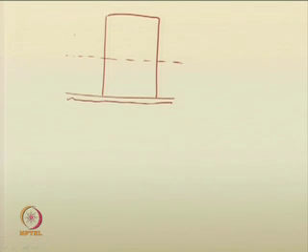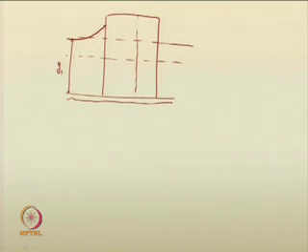So, various flow depths we can suggest now. Say at section 1, let us assume that it has the normal depth y1, then the flow rises due to the obstruction, it reduces to a certain value here, then it rises like this. So, this is depth y3 at the section 3. So, this is the obstruction.